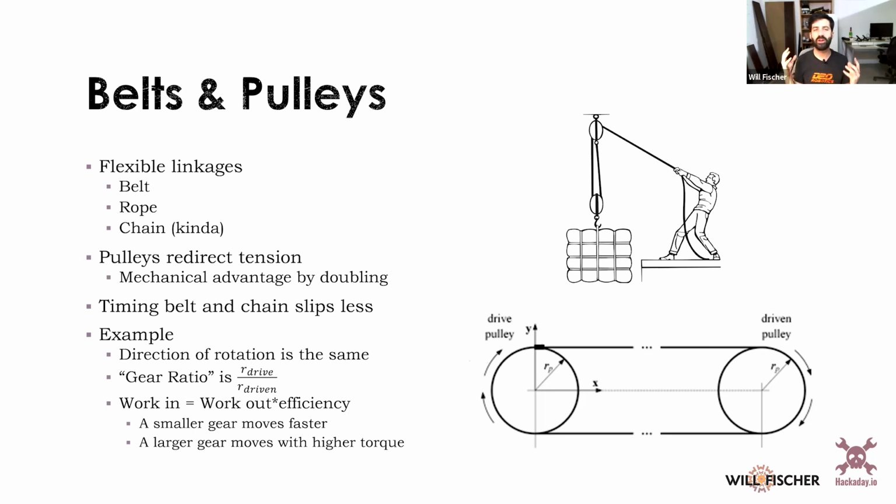And the fundamental of this is that they operate great in tension, but as you compress them, they buckle basically immediately. If you think about trying to compress a rope, you pull it taut, it stays great in tension. The moment you go like this, it's already buckled under the force of gravity. It's sagging like that, and that's what defines these things. So you can use pulleys to redirect that tensile force. Pulleys do not redirect compressive forces.